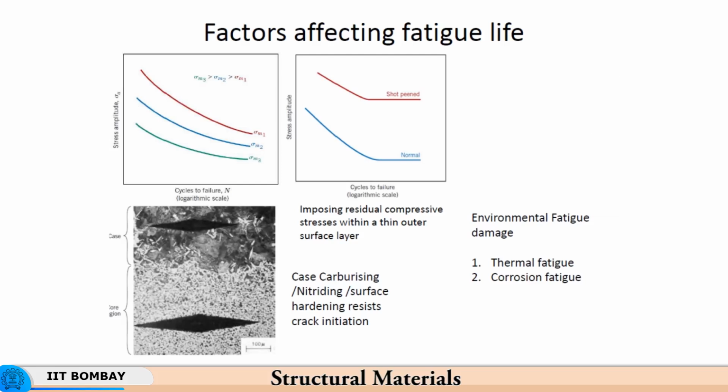Now, together with this, there is another kind of fatigue damage, which is thermal fatigue. In case of the boiler, about which we were discussing earlier, there is thermal fatigue. In addition to that, there is mechanical fatigue arising out of fluctuations in pressure, fluctuations in temperature, and then add to that the corrosion taking place from time to time. That is because the water inside the boiler has a certain pH. It is usually not exactly 7. It may be slightly acidic, slightly basic, but not exactly 7, due to which a very small amount of corrosion could also take place.